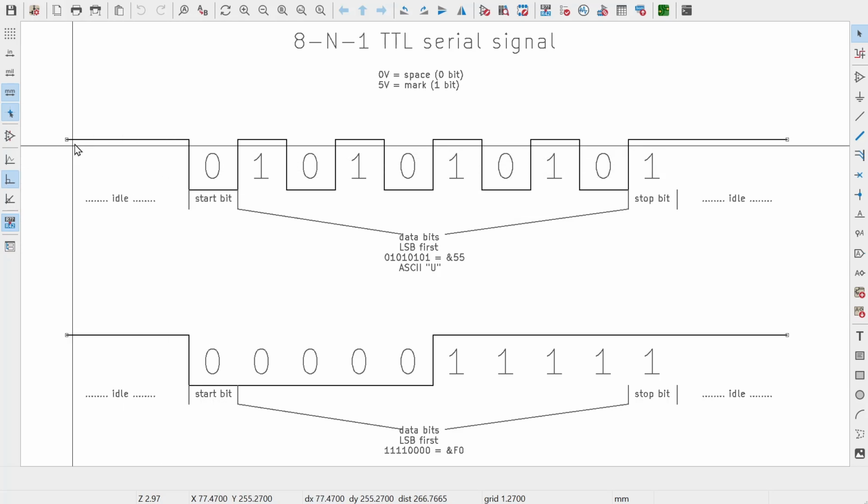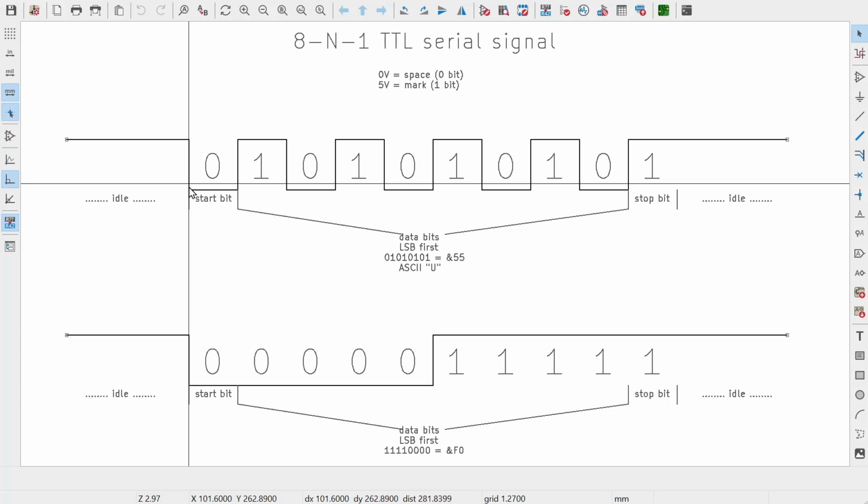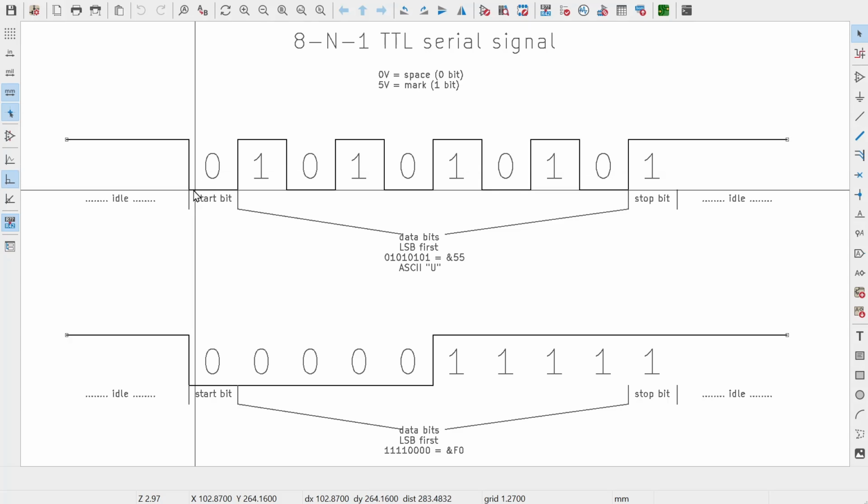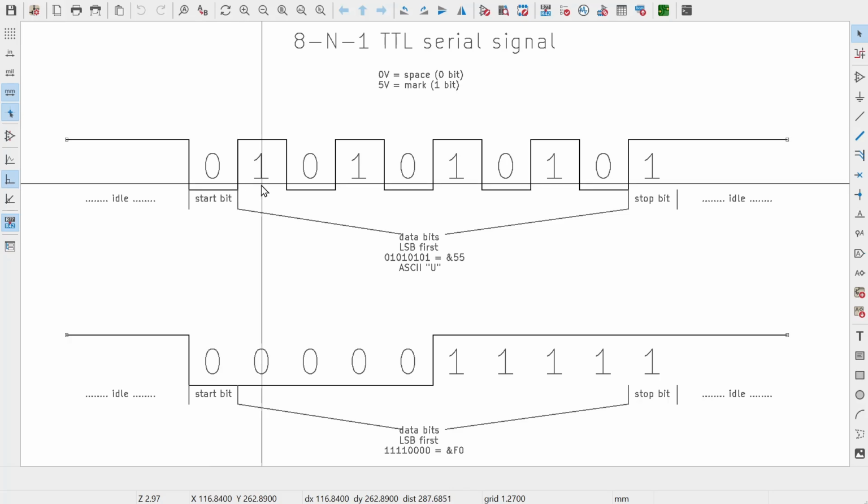So what we're going to be doing is all the way during this period we're going to be sampling once every 4 megahertz, looking out for this downward transition on the received data line, and when we find it we're going to reset a counter, and it's going to count down from however many 4 megahertz ticks it is until the middle of this bit, and that's going to depend on the baud rate.